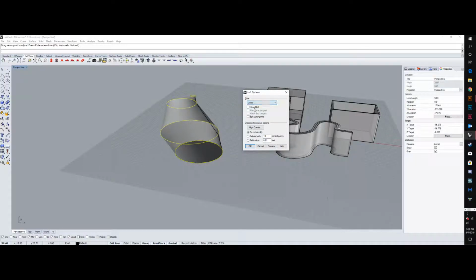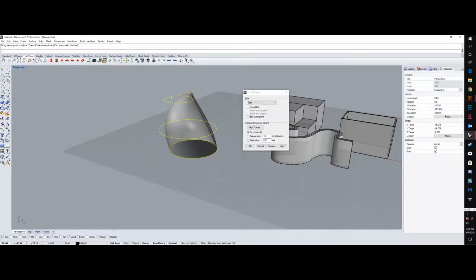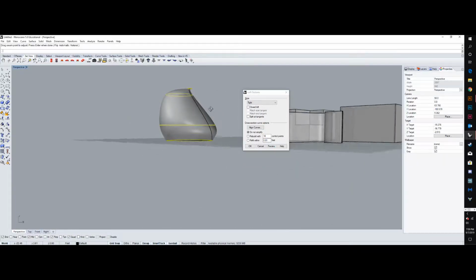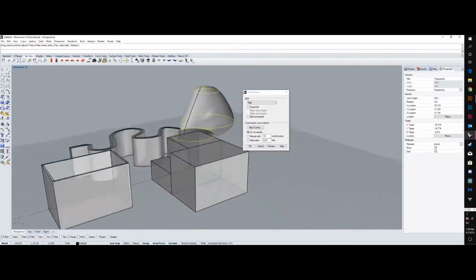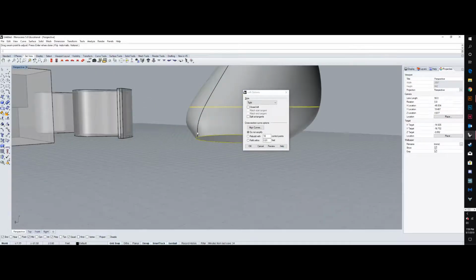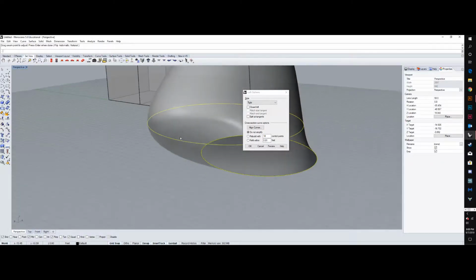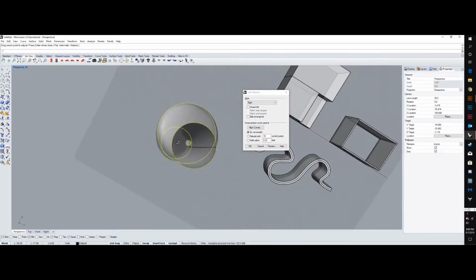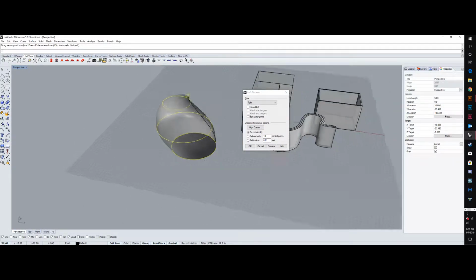Let's try the loose, get it a little more curvy or tight. So you notice that loose doesn't really stick to the contour as much. I can try tight, which will definitely stick to the contour. It'll hit these contours where you tell it, but in order to do that, it will also bulge where it needs to. It'll cause bulges wherever they may be needed, and you'll get a more accurate form. I like this form because it's more accurate to the lines I told it to hit.